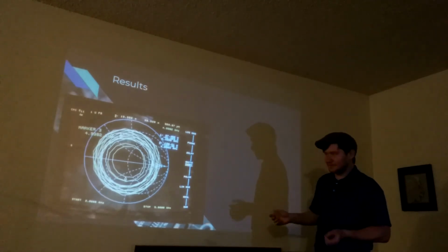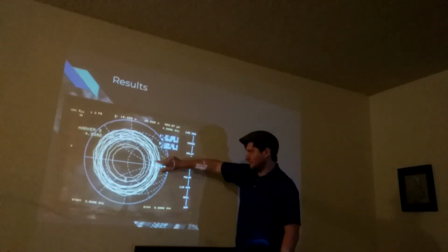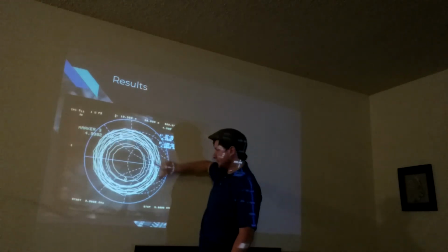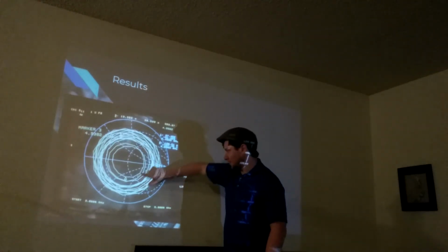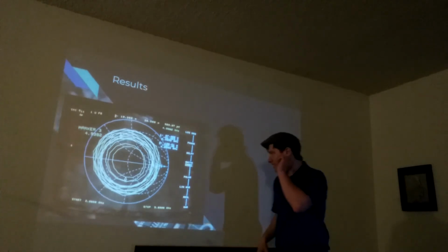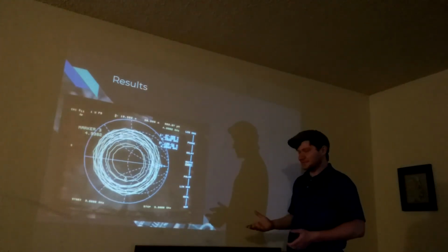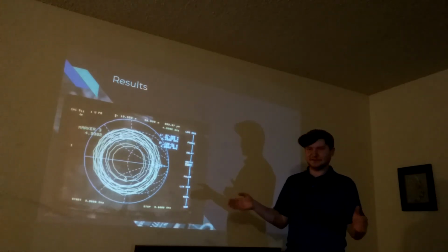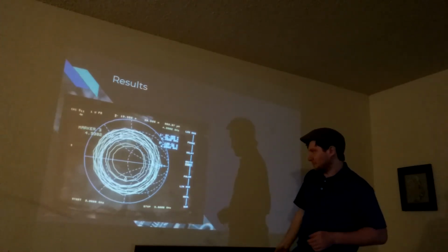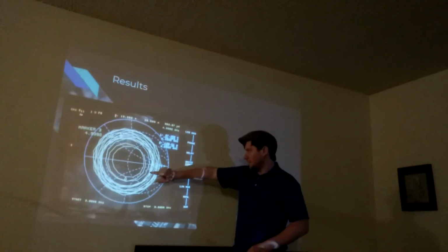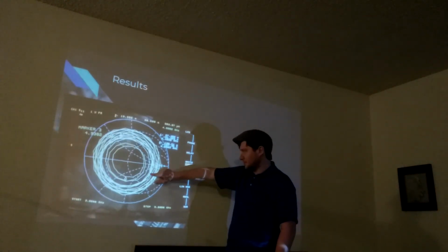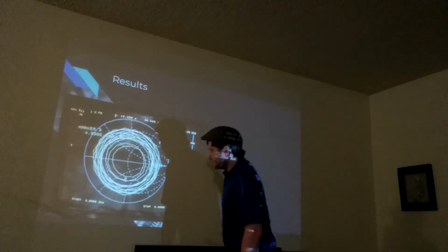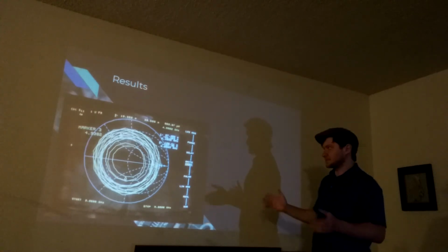Now, if this was perfect, I think that the response would be almost just one circle instead of going in a little bit and out a little bit. And that means that there would just be one voltage standing wave ratio over the entire range of frequencies that I was designing for. This seems really apparent for the 3 to 4 gigahertz band right here, where it's just one solid circle, and that's where I was saying that was mostly flat.